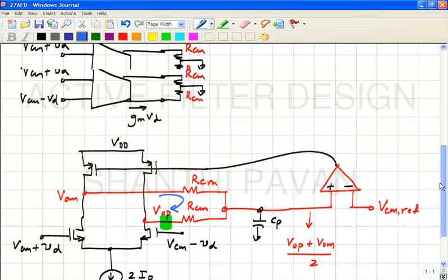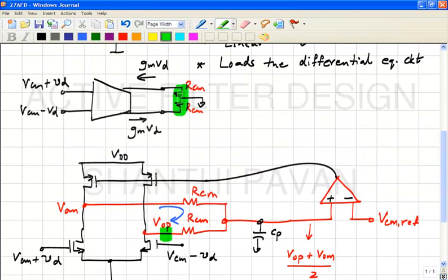Ideally, why is the resistor a problem here? Because the transconductor is putting out GMVD, some current has to flow through those common mode detecting resistors. So, some part of that GMVD is getting lost. In simplistic terms, that's the problem. So, how do you fix the problem?